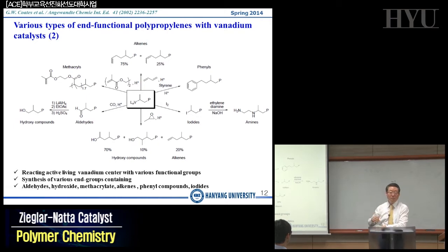Your ink system usually is two types of ink systems, which is organophilic or hydrophilic. Okay, organophilic or hydrophilic. Hydrophilic means aqueous systems. Okay, polypropylene does not have any bonds to incorporate the water, so it's not possible to make the hydrophilic ink coating on top of your polypropylenes.